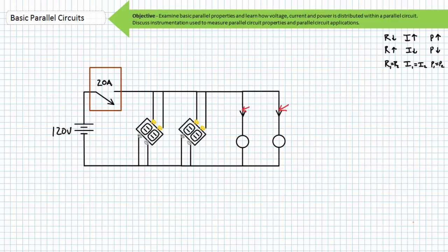This might explain what I'll call electrical anomalies experienced by those individuals that live in old houses, remodeled houses, or houses simply wired by rummies, junkies, or tweakers. When the circuit breaker for your kitchen pops, does it turn off your bedroom lights? It shouldn't. This is known as functional isolation, in that parts of a circuit or a system are protected from the failure or malfunction of associated or contiguous parts. Ideally, each bedroom, bathroom, kitchen, garage, heating or cooling system, or room should function independently of one another.